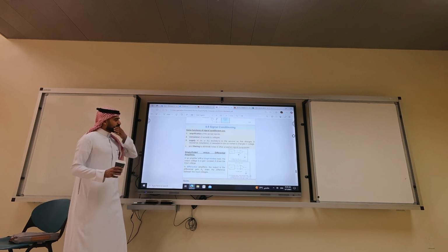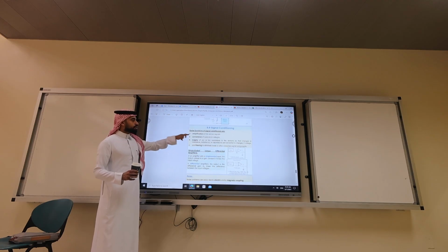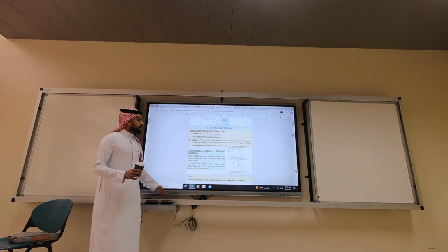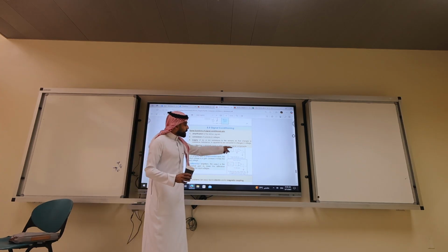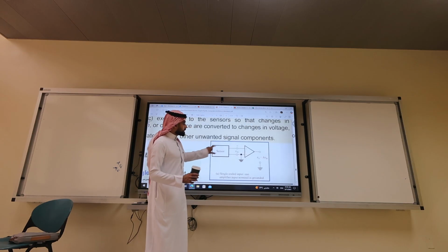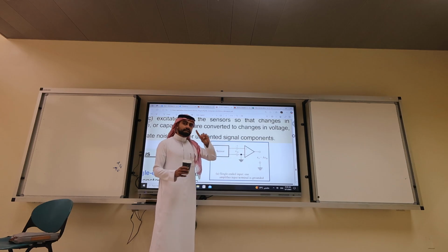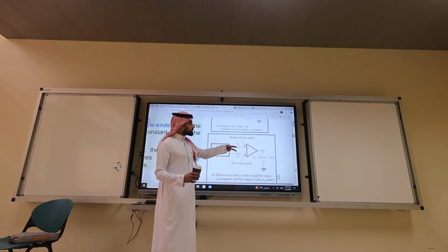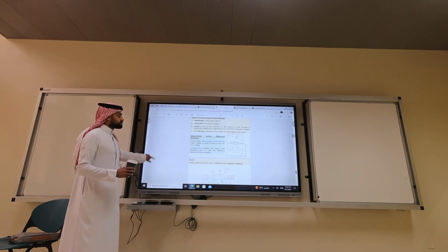For the signal conditioning, the purpose is to amplify the signal, convert current to voltage, supply necessary electricity, and filter out the noise. I already explained that. How to do it is usually we connect it with op amps. If you connect the op amp with the ground, for example, sensor, and then you connect the inverting input to the ground, then you will have Vn. This is not a closed loop signal. Or you can take the differential input. Both approaches are acceptable.